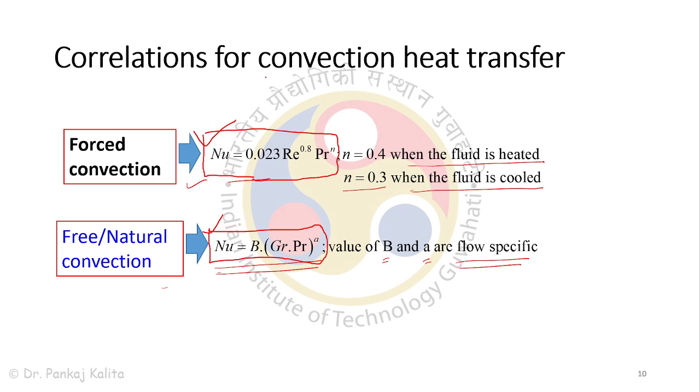Now, note that this n is based on whether heating or cooling is taking place. If the fluid is heated, then n is 0.4. If cooled, then it's 0.3.